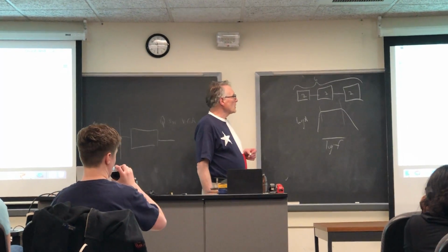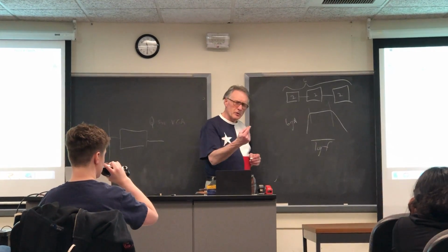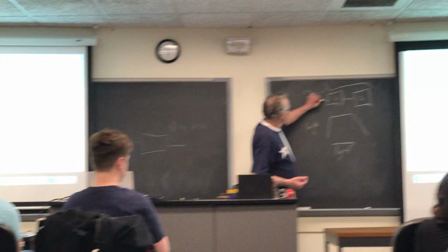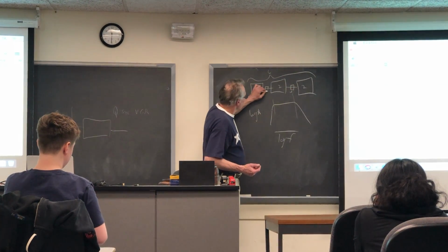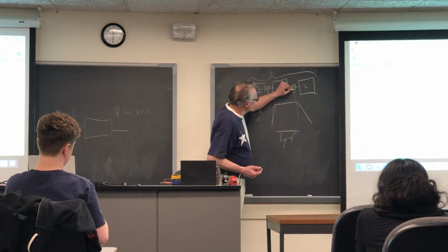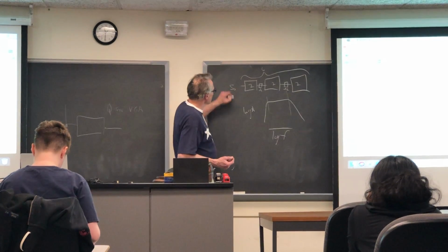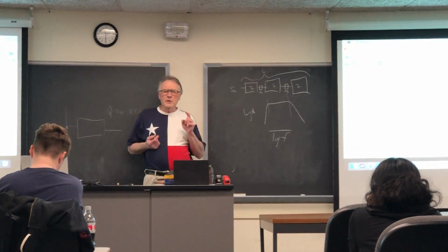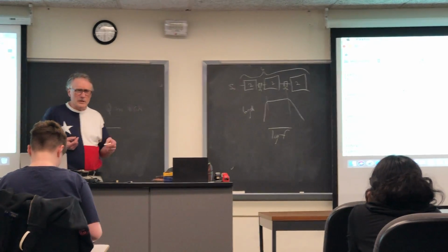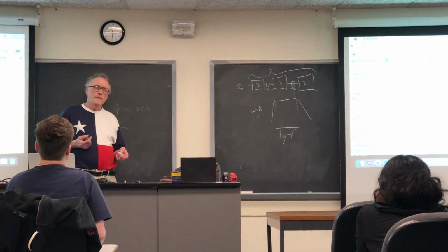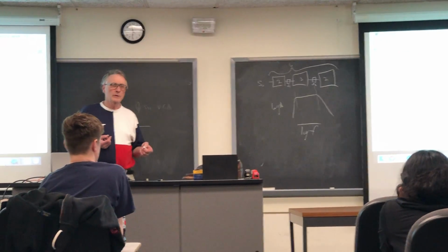So it turns out that this particular kind of filter requires a scaling multiply between each stage and even one at the input, in which all of the numbers, all of the signals are scaled by a number like 10 to the minus 4. That's hard to do in fixed point, but trivial to do in floating point.